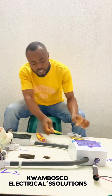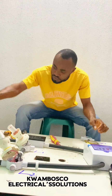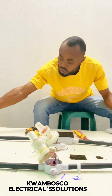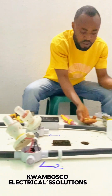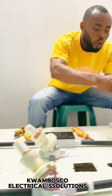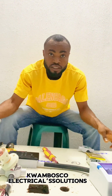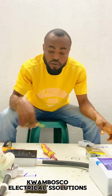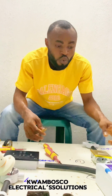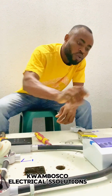So in such cases, you look very well, this one is showing, this one is showing. Now what you do is, you don't loosen all your electrical fittings, because let's assume you have like 50 sockets. You won't use one day to loosen all of them to look for the fault. So what you do is, you switch off everything and you come to your distribution board.